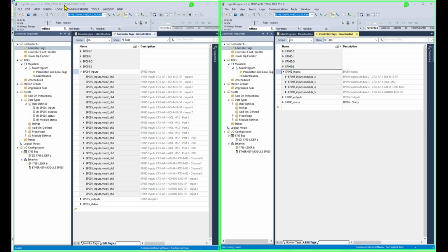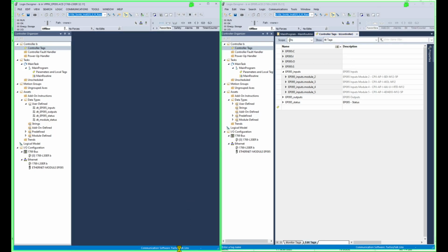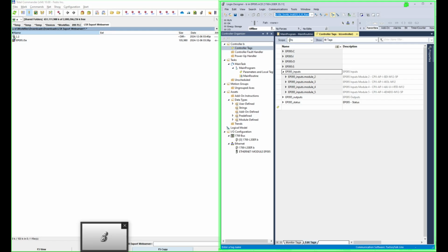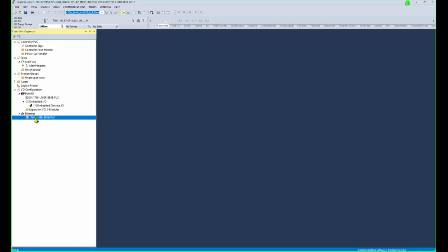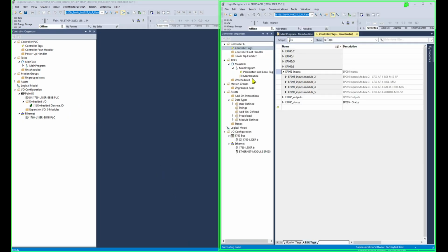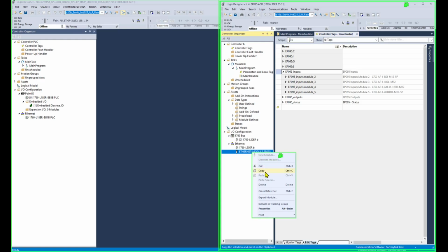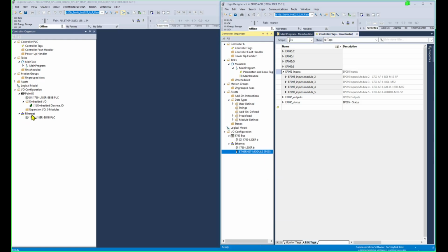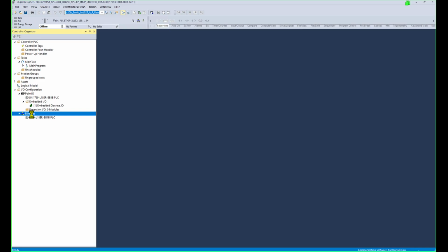So I'm going to close the VPPM from the Festo Automation Suite, and I'm going to now start a project with a PLC in it. So this is my PLC project. So this is your project, and you want to get the new information into the project. We would simply come over, copy this Ethernet module, come over to the Ethernet, Control V or right click, paste. You could also do a paste.